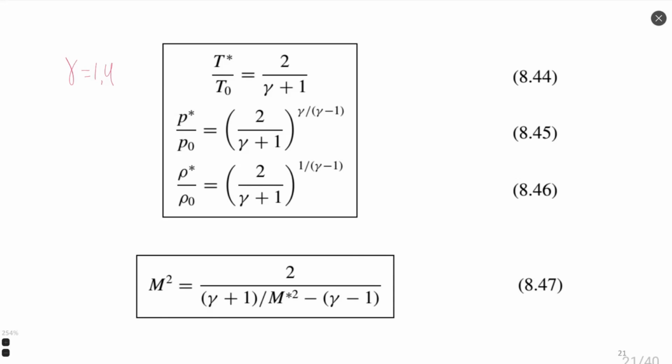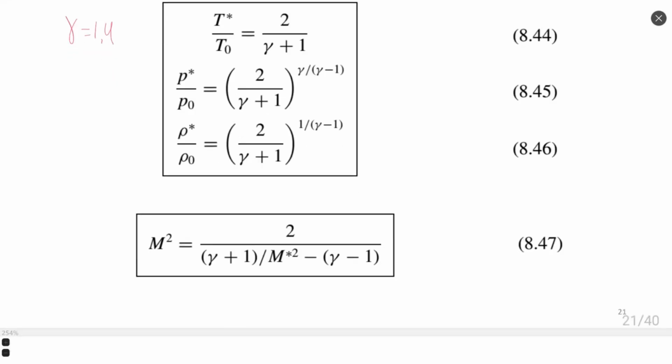Just closing this question, I want to tell you that there is always a transition formula which allows us to calculate flow in terms of Mach number and characteristic Mach number, formula 47. Characteristic Mach number M asterisk is velocity divided by the characteristic speed of sound, which is constant for our system.